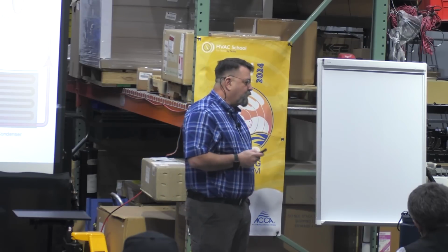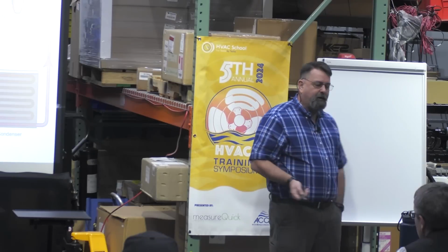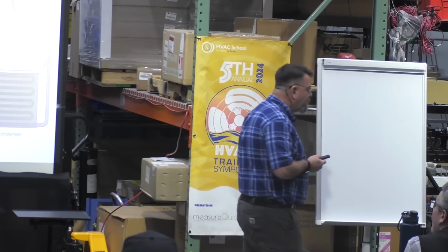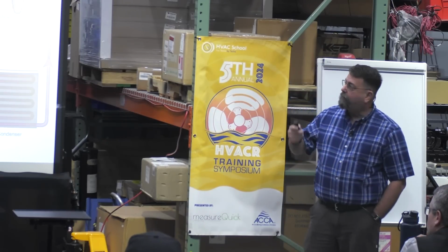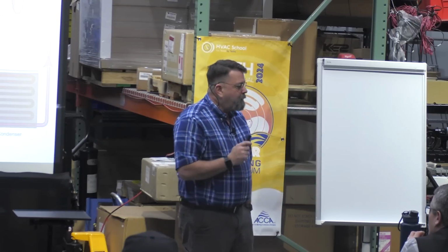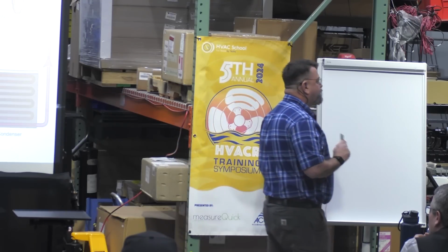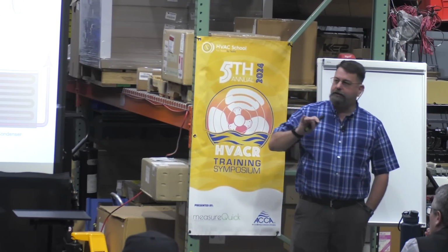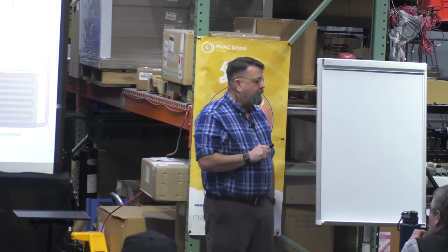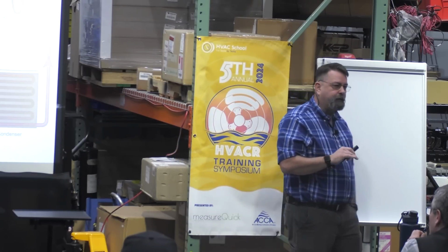Okay, so my evaporator is the same. I've got a metering device. I'm going to blow air through there, right? I'm going to bring heat to it via air. It's going to absorb that heat, boil my refrigerant, right? I've already covered that. We're going to do exactly the same thing, right? But one of the differences is, I told you we can't adjust our charge to control our suction, right? Suction is everything in this game, in refrigeration.